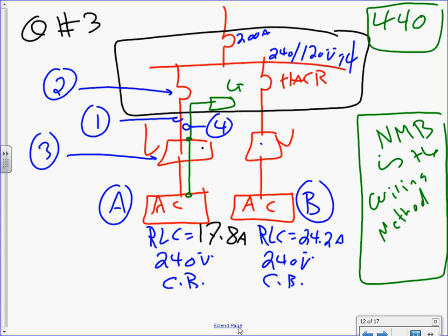Most people get confused because they don't use the right terminology. I'm sizing the wires. What type of wires is that? You know what I mean? I'm sizing the branch circuit conductors. And then after you size the branch circuit conductors, you have to refer to what type of wiring method you are using, because based on the wiring method, it will force you to size them differently. If you're using an NM cable, you're forced to go to 60. If you use an MC cable, you can go to 75. So the wiring method is a big deal.